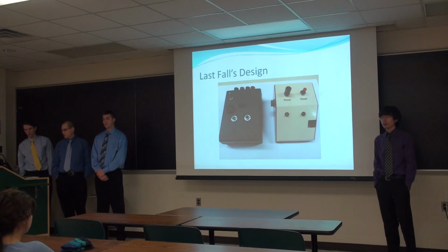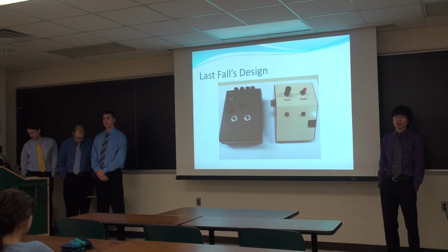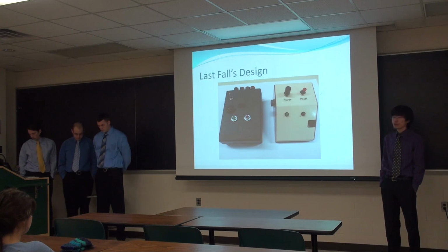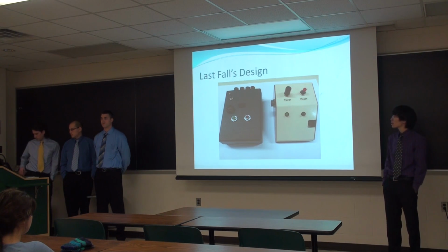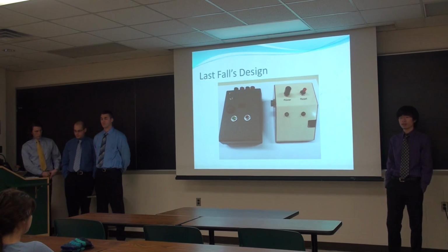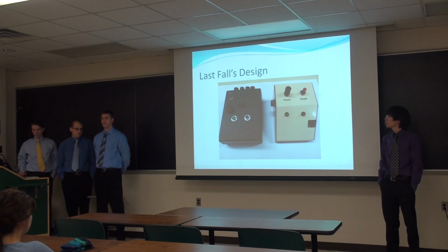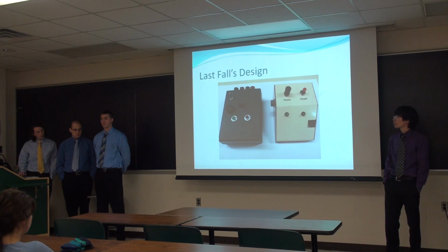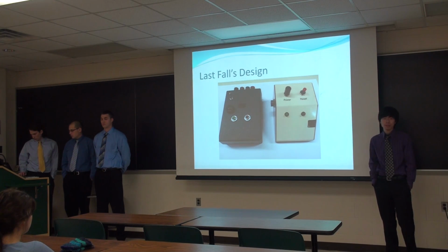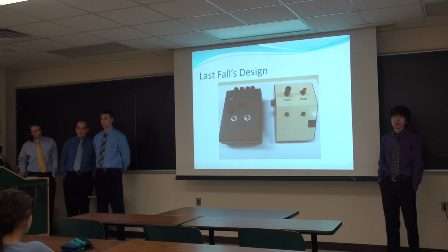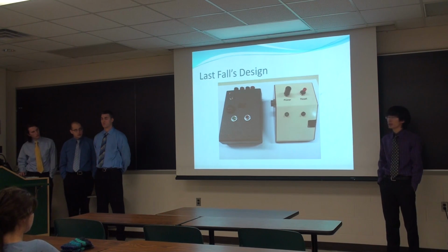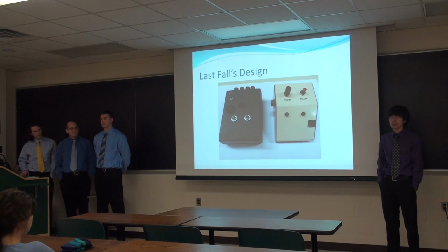And for the last fall, there was another team sponsored by Instrumented Sensor Technologies doing a 3-axis cutoff sensor, and they will have a preset value for the 3-axis accelerometer. Once the accelerometer meets that value, it will just cut off the relay, like a safety switch. However, our team is using a 1-axis accelerometer, and we'll do data processing in between. We'll have peak code and RMS calculation. So we'll have more work involved versus theirs.